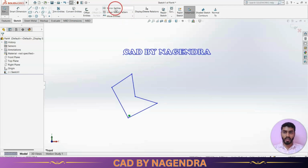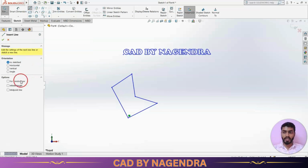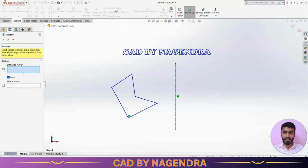Now let's see how to use this Mirror Entities. To use it, one mirror center line is required. Now by using the line tool, I'll create one construction vertical line like this. With reference to this vertical line, whatever shape we have here, we need the same shape on this side. In that condition, we can use Mirror Entities.